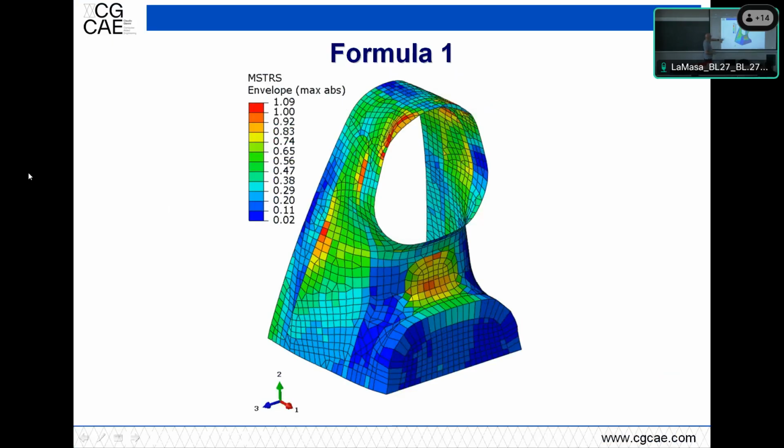And you see, this is the failure index. So it's a sort of contour like the von Mises stress, but for composite structures. It means that when you have one, it's failing. So you would like to have everything which is below one.